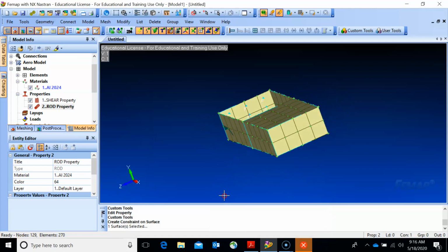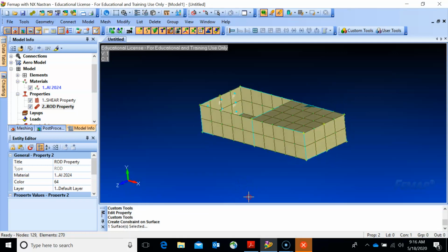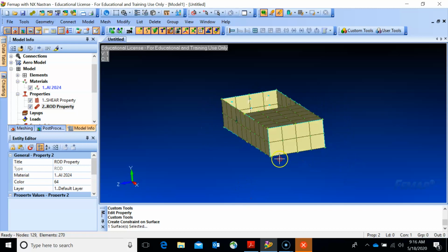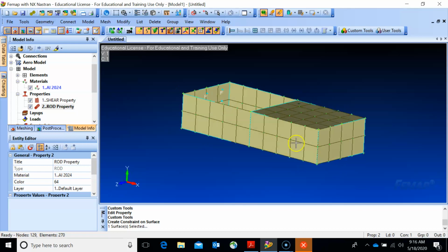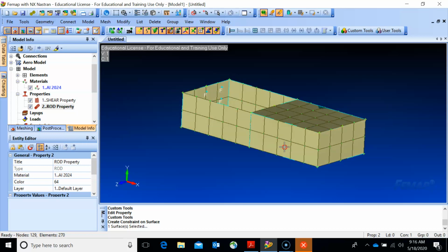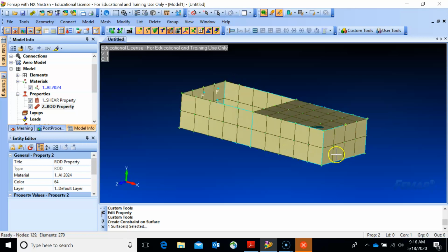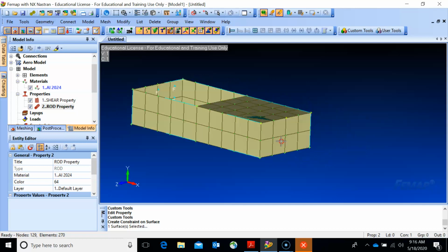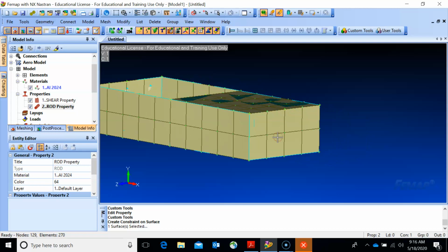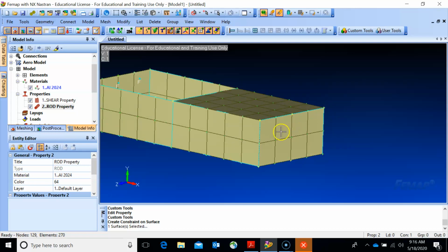Now we need to apply the loads over here. There are different ways. I think you could apply the load on the middle node, but I don't know if that's going to deform this one, so it might affect the loading. So the way I will do it doesn't mean it's a correct one. I will try to create what they call a spider web over here. It would connect this edge, this edge, this edge, and the other edge to our center node.